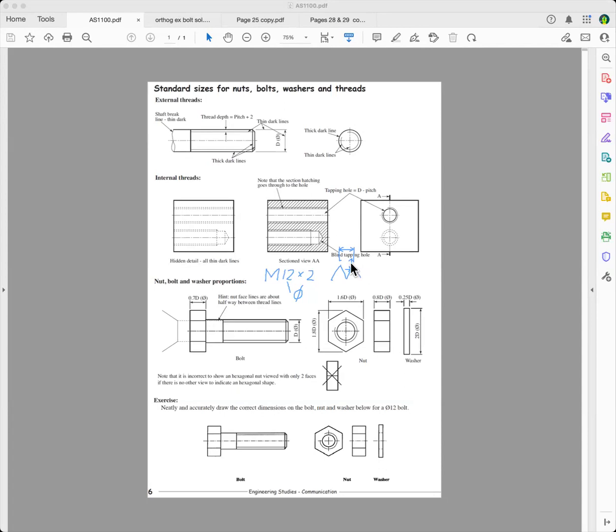And that's called the bursting force on a nut. And so you've got to have the nut thicker than the head of the bolt because of the bursting force caused by the angle of the thread.